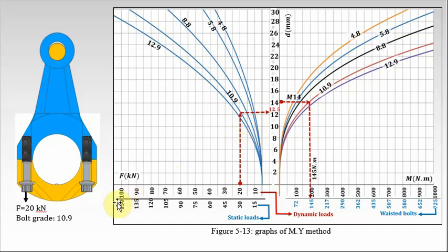At first, because the force in machine elements varies from 0 to the related force in the pistons, it's recommended to always use dynamic loads in machine elements. Therefore, from the dynamic loads, select the applied force.